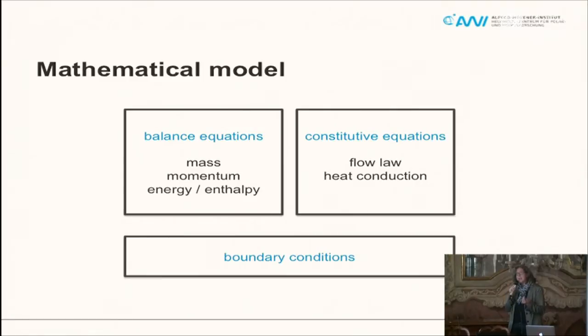In our case this is a rheology describing a viscous flow, because the material ice consists of many small grains that are deforming, and it is a very viscous material with certain properties. It's softer if it's warmer, and the faster you deform it, the softer it gets. It's a little bit like ketchup. You shake a bottle of ketchup in order to make it more liquid. And that's the same type of behavior that you find in ice.